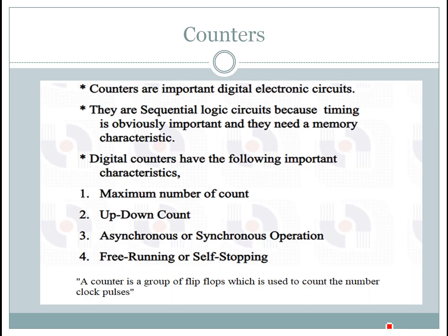Counters are important digital electronic circuits. They are sequential logic circuits because timing is obviously important and they need memory characteristics. A counter is defined as a group of flip-flops which is used to count the number of clock pulses. And these digital counters have some important characteristics. They are: first one is maximum number of count.